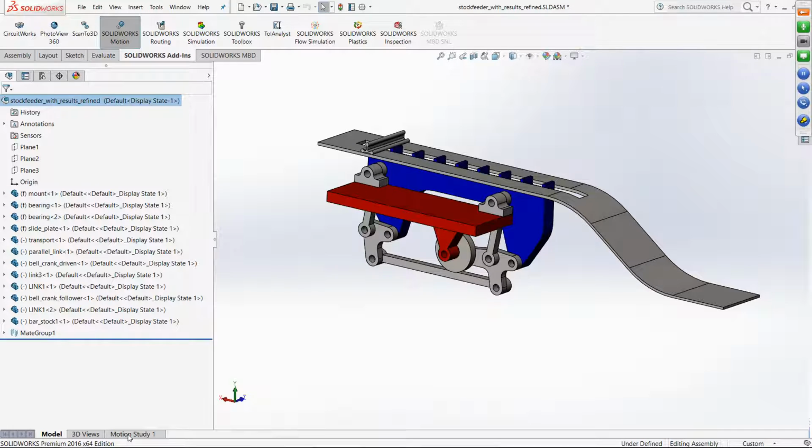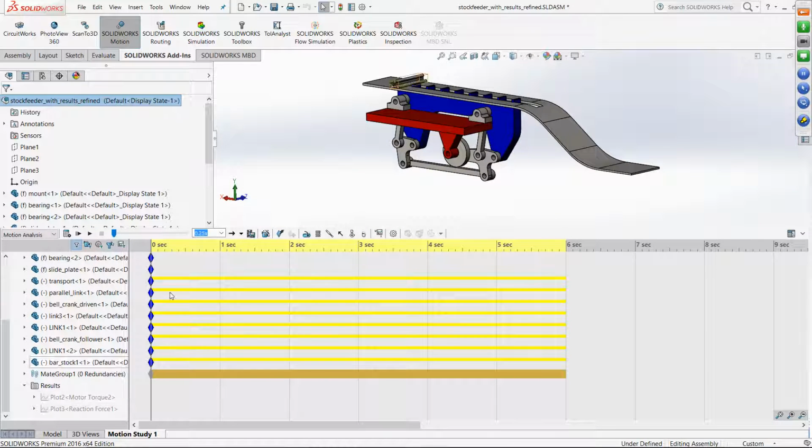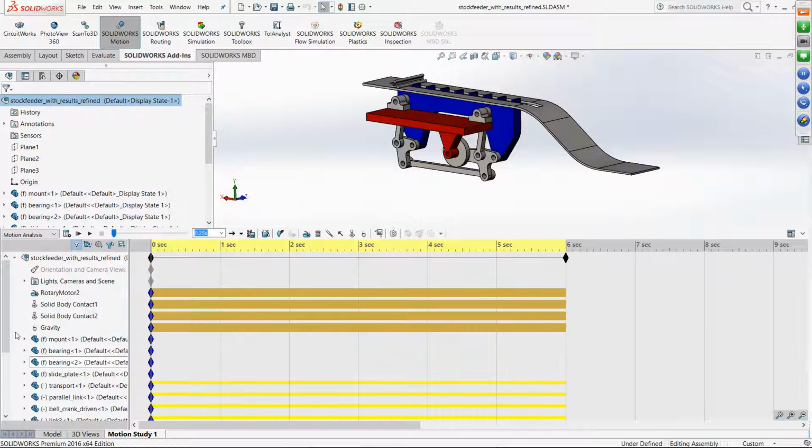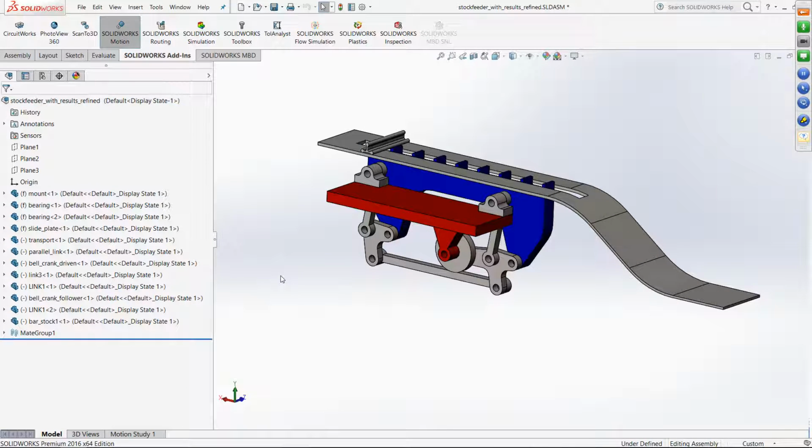Assembly, we are quite comfortable. The motion front end is quite easy. You just follow through certain things. We are using all design words like motors and springs, stiffeners, dampers, etc. So those can be used directly. And finally contacts. So this is how it works. This is how we create the setup, and this is how you can simulate such a mechanism.